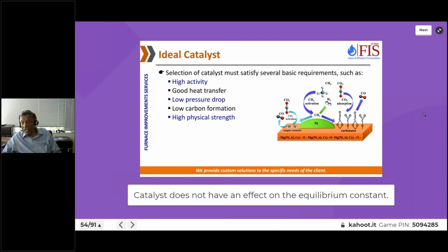One of the things which happens in the catalyst is anytime you have a shutdown of your steam reformer, the expansion and contraction of the catalyst takes place. So every time you do that, you will have some breakage of the catalyst. And generally, the reformer pressure drop will continue to increase every time, maybe by about 5%. So those are some of the things. And the conditions are so extreme, you want high physical strength, you want high activity, all these type of things is what you need.